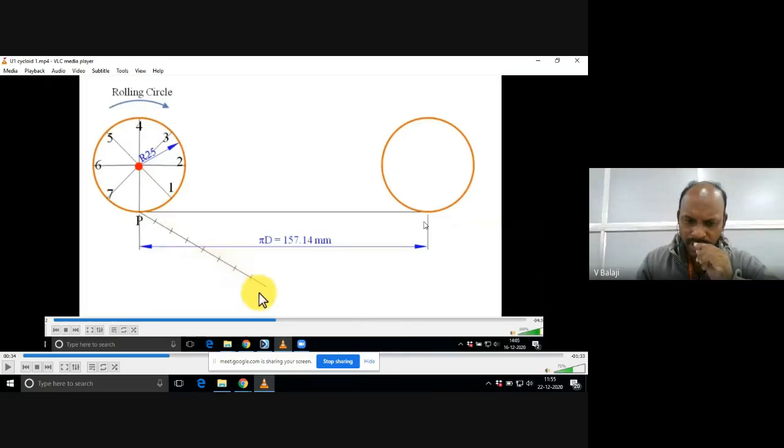And remember, except this cycloidal curve, all other lines must be 2H pencil only. All other lines must be 2H pencil only, except the cycloidal curve. The cycloidal curve must be drawn with HB pencil.